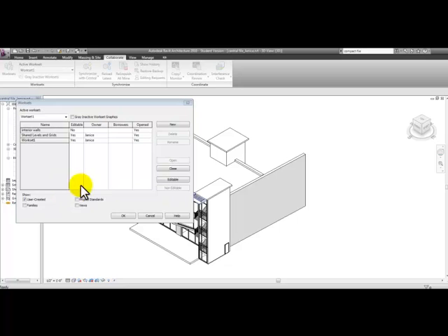This is the central file, in which Revit creates two default worksets: Shared Levels and Grids, and Workset 1. In the local file, I created another workset called Interior Walls, and that's why it says No, that you won't be able to edit it, because it's already checked out in one of the local files. Revit also creates worksets here at the bottom left for families, project standards, and views.